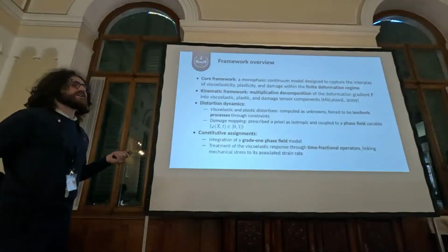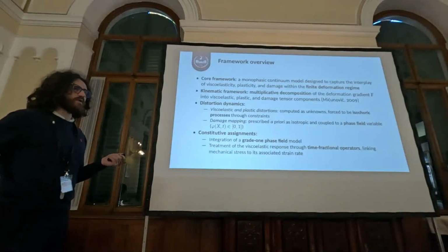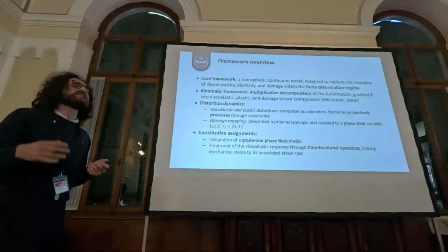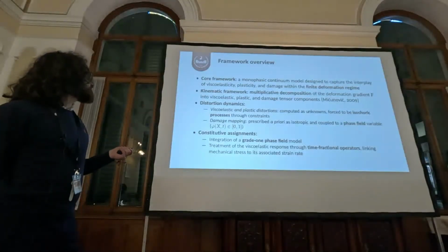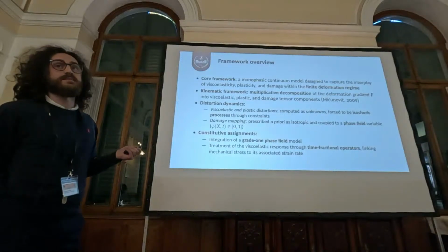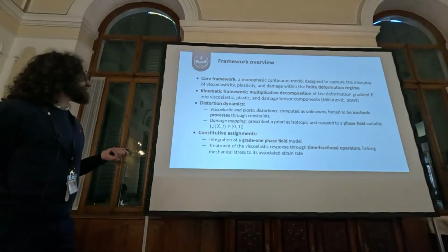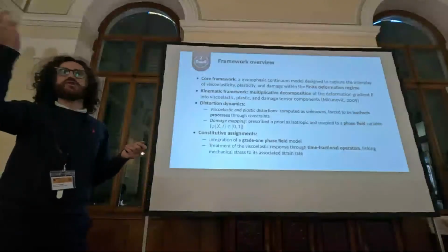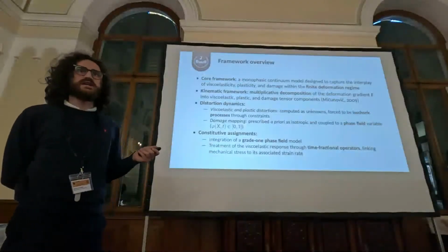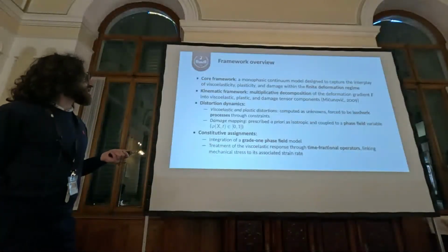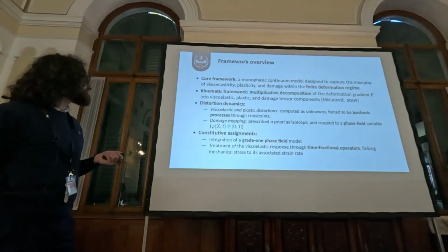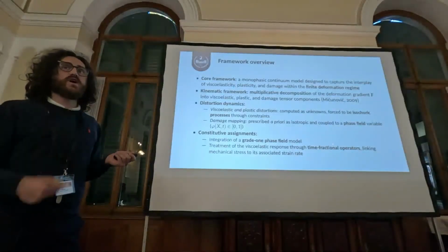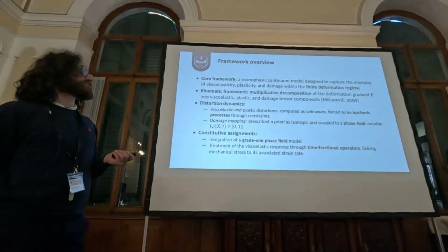So after the calculation of the force balance laws through the principle of virtual power, we have to do some necessary constitutive assignments. We will integrate a grade 1 phase field model, as happens in the vast majority of the literature about phase field models in fracture mechanics, and we will treat the viscoelastic response of the continuum through time fractional operators.